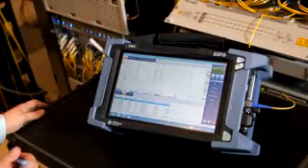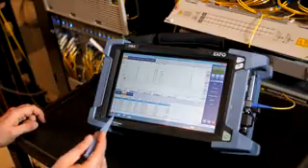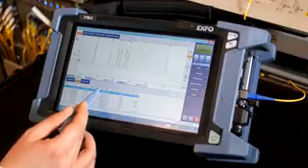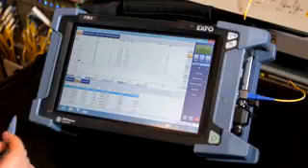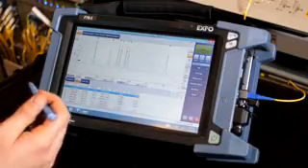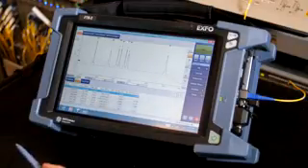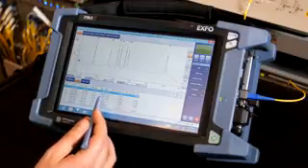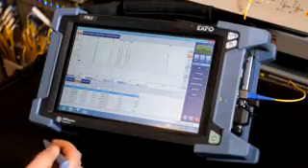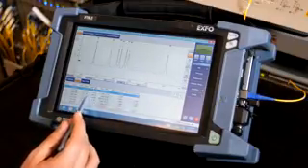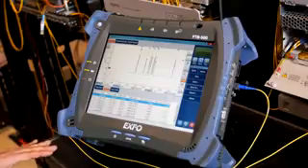Now the in-band OSNR measurement is completed. For all the channels that are not polarization multiplexed, that is the 10 gig channels in this particular system, I see the noise type. The question marks tell me that for these channels the in-band OSNR analysis couldn't be made, and this is normal because these are 100 gig or 200 gig channels. So channels 2, 6, and 7 will have to use another method. But for channels 1, 3, 4, 5, the in-band OSNR method has been applied successfully, and I get OSNR values around 27 dB.